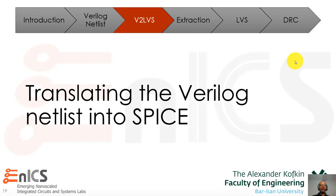And here we're going to start the third part of our Digital on Top Physical Verification lecture. At this point, we're going to translate the Verilog netlist into SPICE. As I remind you, in the last two lectures we first showed a general overview of our LVS process, and then we showed how we extract the Verilog netlist, fixing all kinds of problems. So we now have a Verilog gate level netlist.